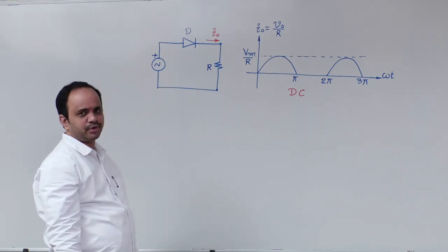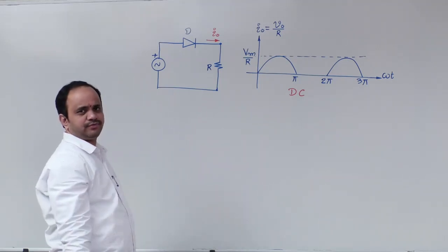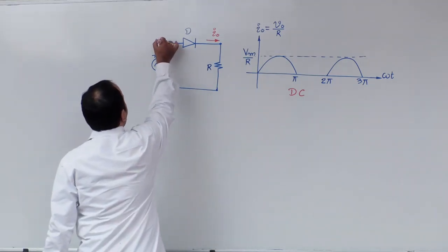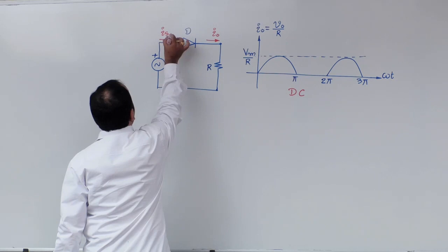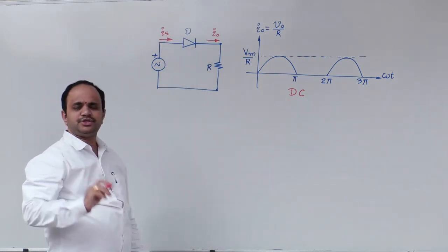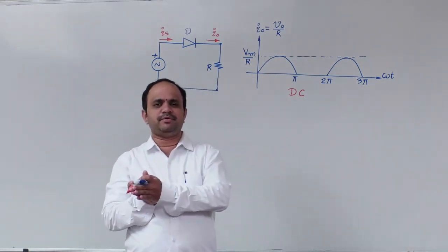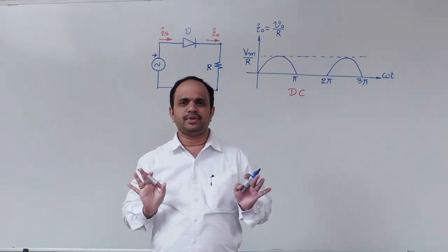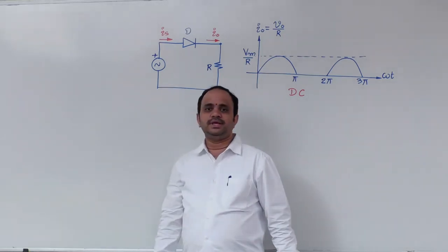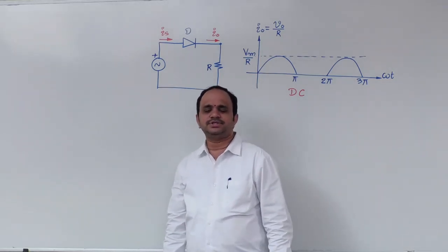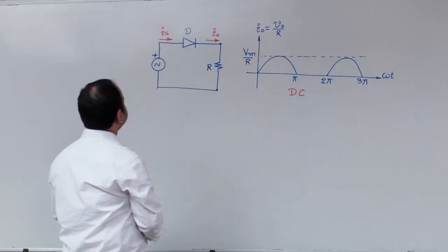It has a DC component, right? Of course, it is not a pure DC, it is basically a DC waveform. Next, if you look into the source current waveform, now just think about what the source current nature is. Generally, rectifiers means, by the basic definition, AC power to DC power conversion. True. So we can expect that at this stage the source current will have AC nature, but that is not true in case of a half wave rectifier circuit. What is the reason for that?